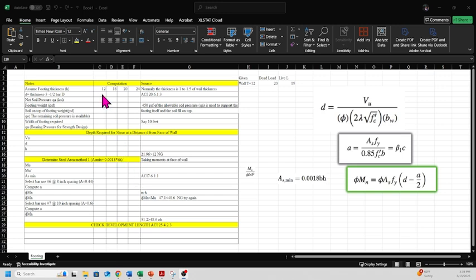And right here, I'm just going to type in equal this minus 3.5, enter, and then grab the corner and go all the way across, and that's what we're going to have for the rest of them. And then the net soil pressure was given to us as 4 ksf, or 4,000 psf, and here I have a 4 ksf, so I'm going to put 4 ksf for all of them.